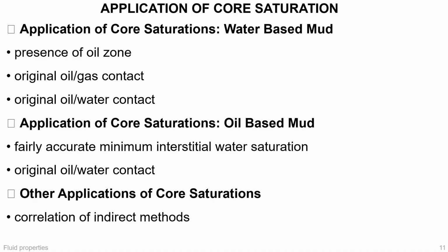With water-based mud, core saturations may help identify the presence of an oil zone and estimate original contacts. With oil-based mud, minimum interstitial water saturation may be more accurate. Core saturation information also helps calibrate indirect methods such as log interpretation and capillary pressure-based saturation models.